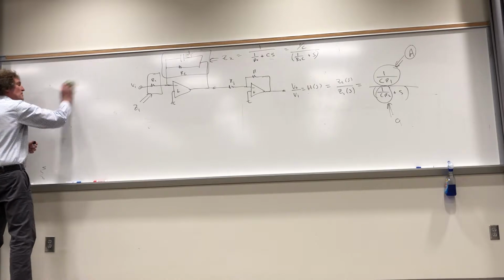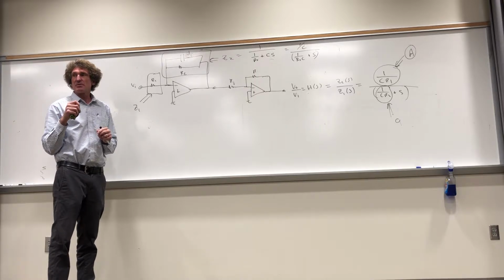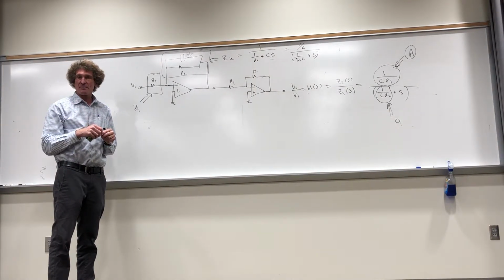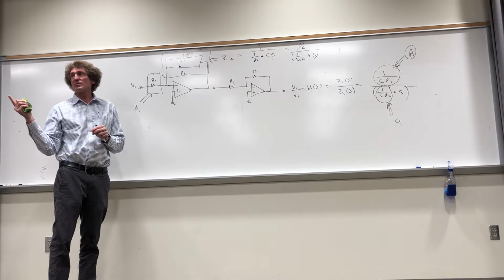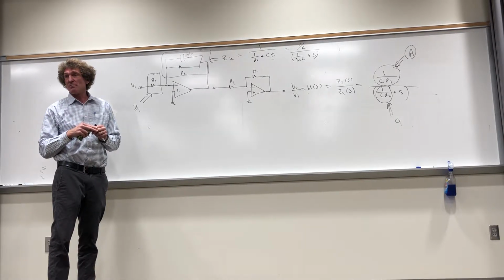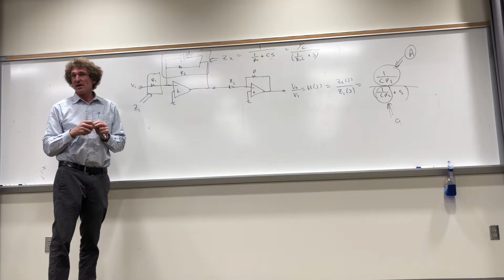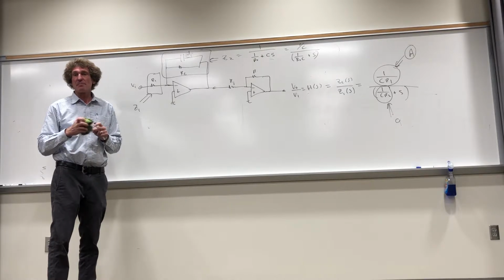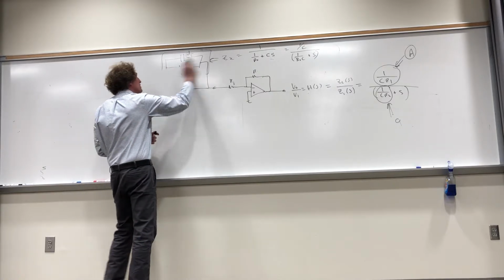One of the biggest things that I remember in labs that I had, a lot of the parts we were given, we had a shop manager, a guy who would work behind there. If you wanted parts, you had to get them and then return them, and they didn't work. So the first thing I always assumed is they didn't work. Second is that the values that were set on there weren't always the values, so I always measured the values. I learned from experience that a capacitor is not necessarily good. I learned transistors don't necessarily work, and that resistors that say they're 100K may not be, for whatever reason. So I always measure if it's important beforehand.